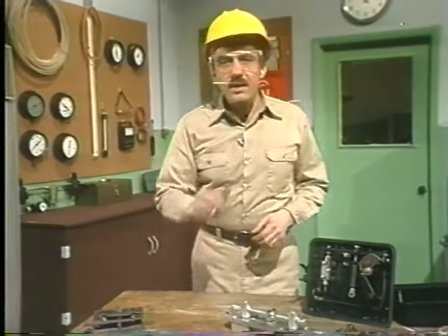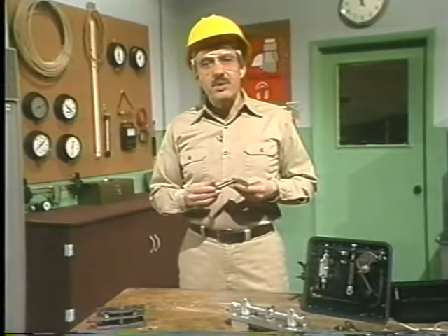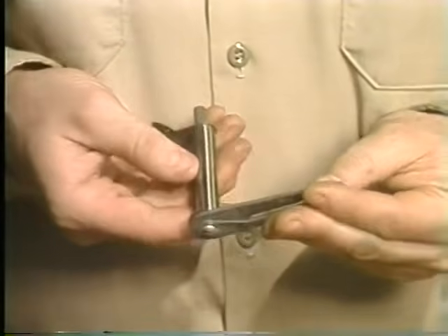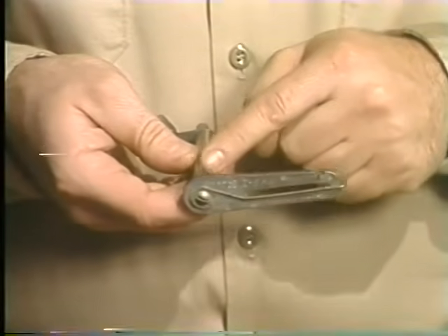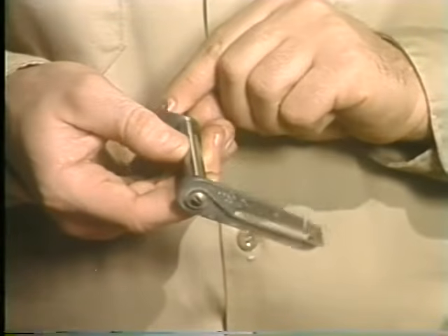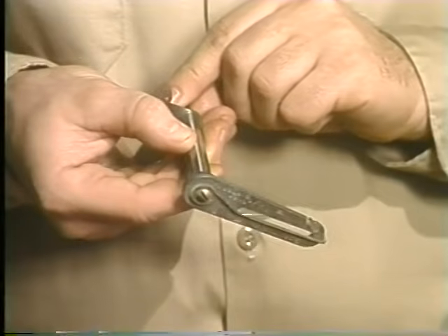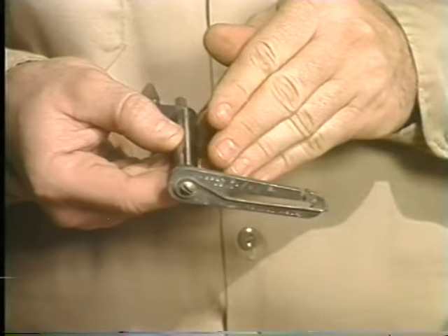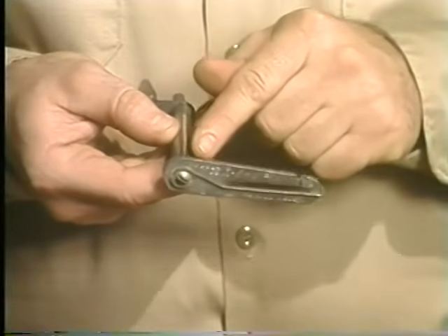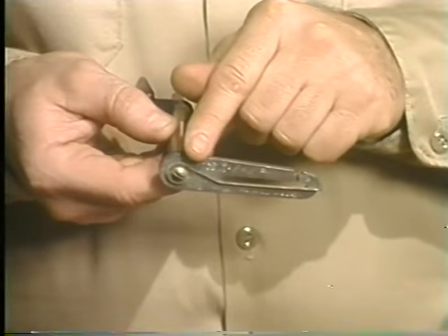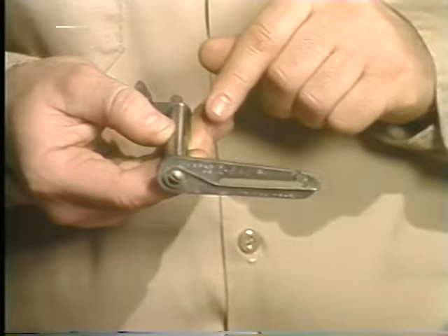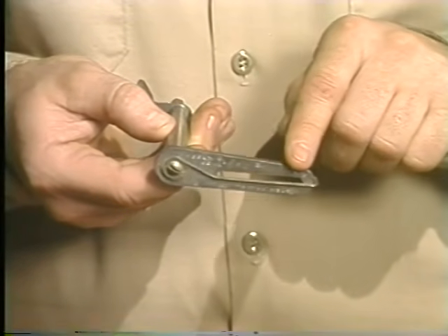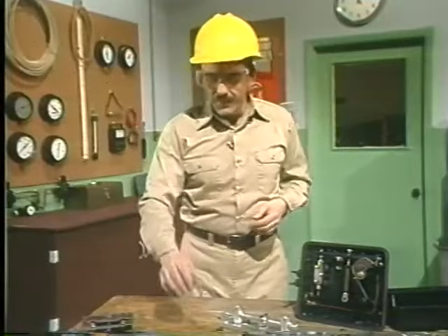Now, this is a one-sided lever. This design more closely resembles the third group of levers. Here, the input comes through the shaft or pivot. As the shaft rotates, the lever rotates. The effort is a result of torque or twisting action applied to the shaft. The input shaft acts as both the pivot and effort force. The output or resistance force is the work that's being done at the end of the lever.